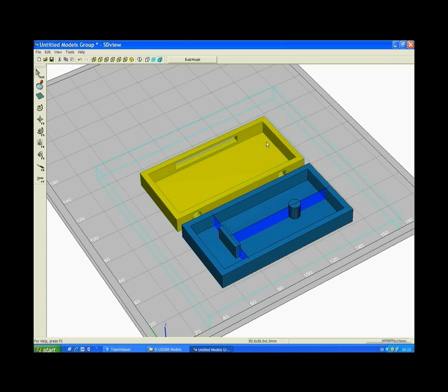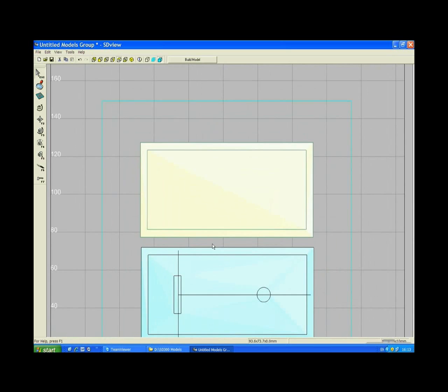In order to divide the areas into the outer part of the geometry and the inner part of the geometry, we will use the peeling cuts to close all openings on the X or Y axis. Again, we will select the top view. We know one opening is just above this area, and the other two openings are just above these areas.